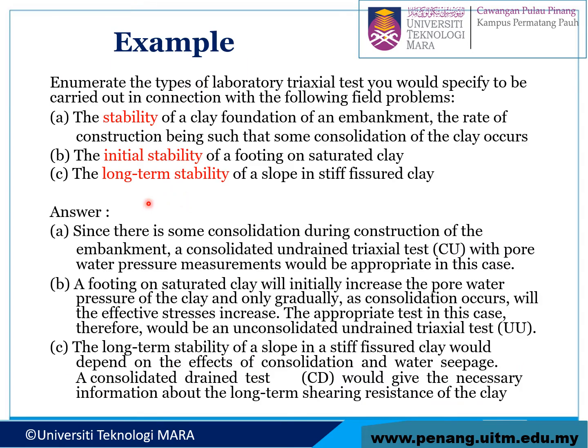Alright guys, we look at these three cases. Enumerate the types of laboratory triaxial tests you would specify to be carried out in connection with the following field problems. For the first problem, the stability of the clay foundation of an embankment, the rate of construction being such that some consolidation of clay occurs. So in this condition we have consolidation. The consolidated undrained triaxial test with pore water pressure measurement would be appropriate for this case.